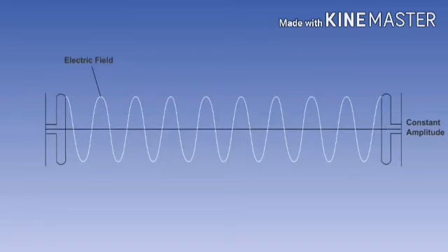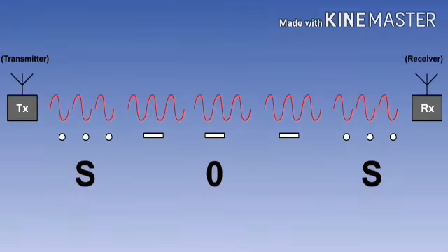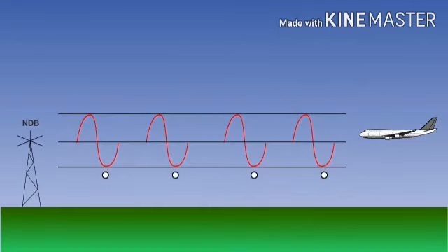As we shall see, in Morse code, it is just simply switching on and switching off of radio high frequency wave, and there is no specific superimposition of any information. The simplest form of modulation is to switch the electric current on and off. This is called keying. Morse messages can be sent in this way. Keyed carrier waves are designated A1A, and they are used mostly for long-distance NDBs, as all of the transmitted power is in the carrier wave.